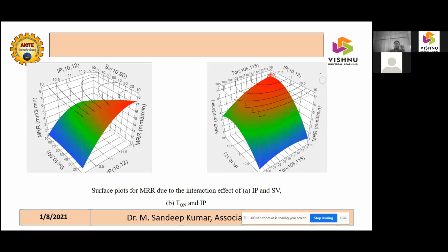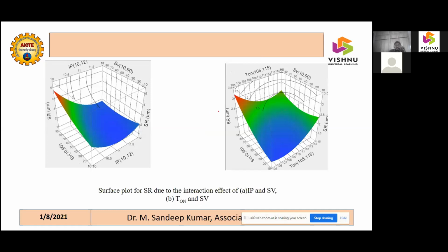No, I want to concentrate only on the surface roughness or surface finish. So what I'll do is, I'll be selecting somewhere where this material removal rate is less. Or if I go to the next graph, I'll select a point where the surface finish is good for me, and at the same time, the material removal rate is good.